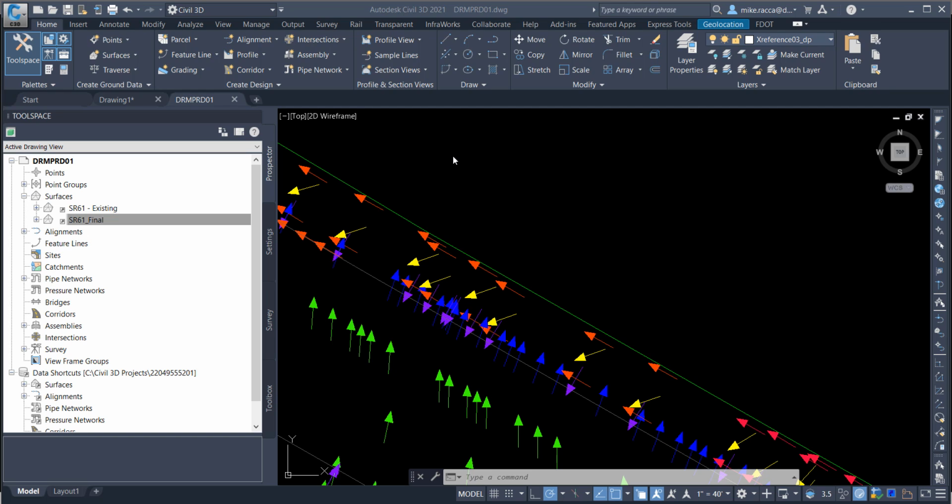Use the water drop command to draw polylines. The polyline defines the water path as it goes from triangle to triangle along the surface. This command draws a 3D polyline from the high point you click to the corresponding low point on the surface. The opposite end of the polyline may be a good location for an inlet. Hint: we use 2D polylines as the path object type because 3D polylines do not display line types.